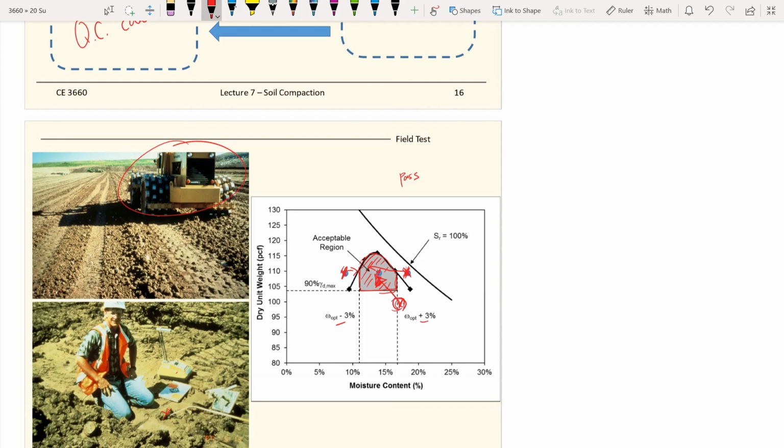So like the line of optimums we talked about, if we increase the compaction effort, it will help us go to the upper left corner. You will get there. So based on your test results, you can give appropriate recommendations on site as technical engineers when it comes to the construction work for soil compaction.